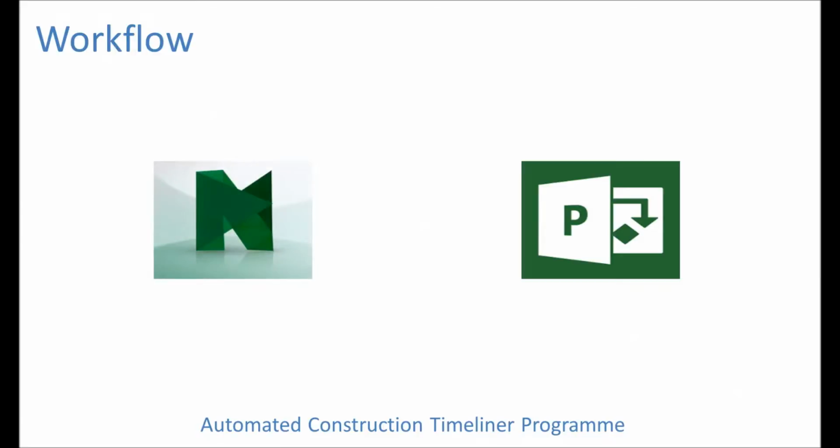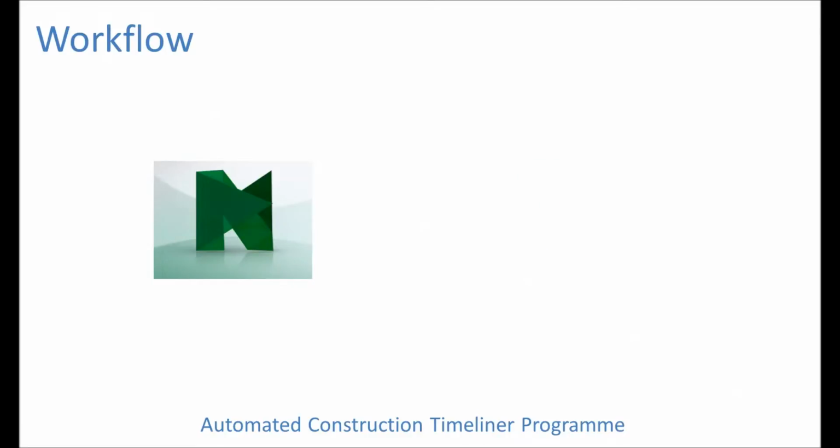We will then open Navisworks, import the NWC file, which we can export from Revit for the relevant project, and import the Microsoft project file. Once all of those are in, we will then use a custom API to map the relevant elements in the Microsoft project file into the correct selection sets within Navisworks. Once it is all done, we will have a standalone Navisworks file.